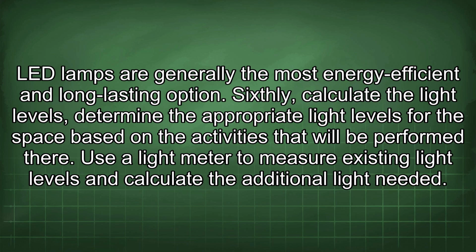Sixthly, calculate the light levels. Determine the appropriate light levels for the space based on the activities that will be performed there. Use a light meter to measure existing light levels and calculate the additional light needed.